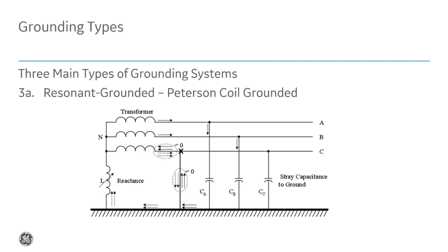And the biggest disadvantage, to me anyway, as a power system protection engineer, is you need to apply special protection schemes for this, because, again, remember I talked about ground fault current being high is not necessarily a bad thing. It's easy to set protection systems for that. For this case, there is no ground fault current, so protection systems require special thoughts and special application.